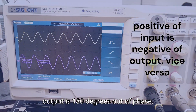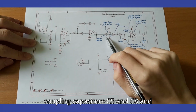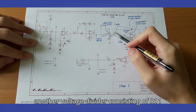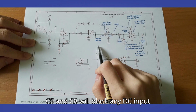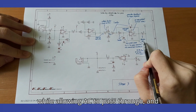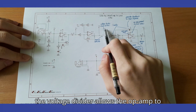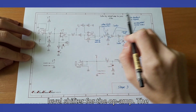For stage 3, we see yet again more coupling capacitors C5 and C8, and another voltage divider consisting of R11 and R12. Once again, C5 and C8 will block any DC input while allowing AC to pass through, and the voltage divider allows the op-amp to work in single supply mode and acts as a level shifter for the op-amp.